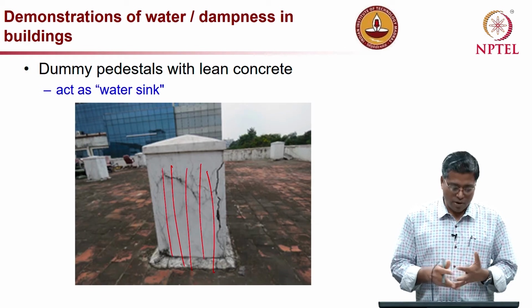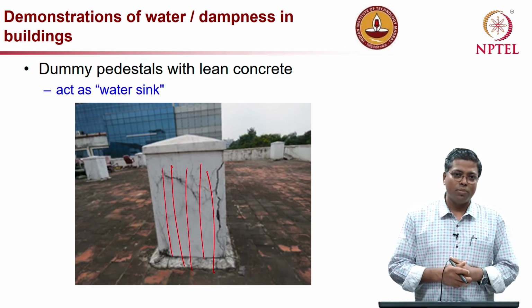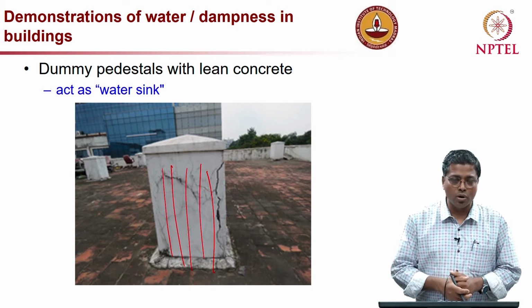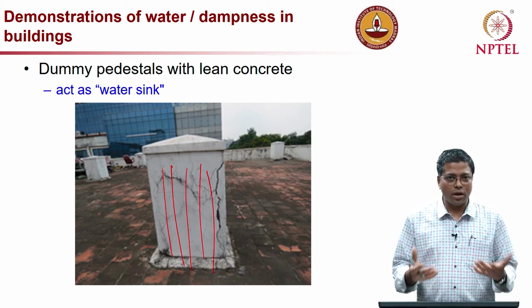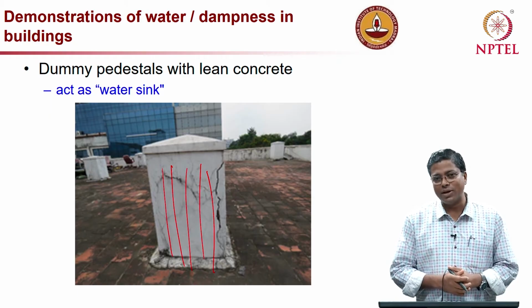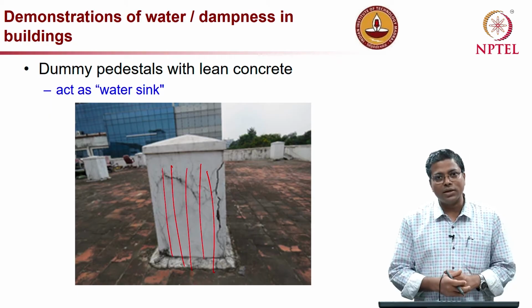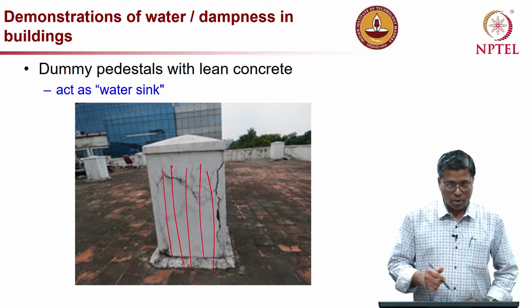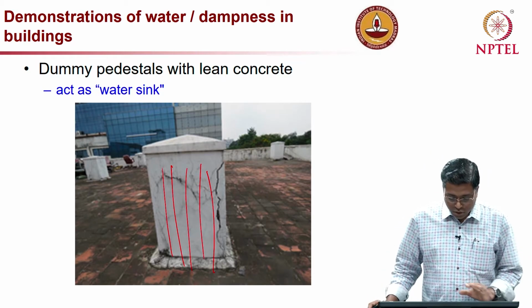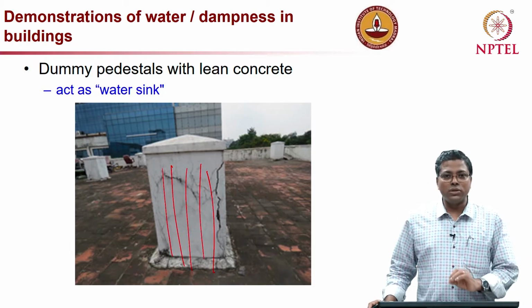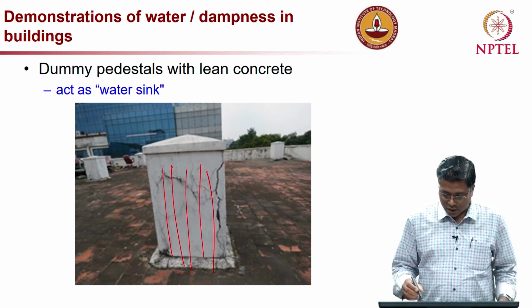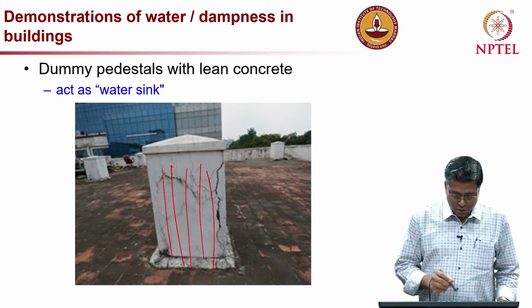And so eventually, when we really want to use these rebars as the rebars coming from the columns below, they are most often found to be heavily corroded, and we end up cutting them and then going for anchors to the columns below. So if we go for this, please go for good quality concrete, not lean concrete. That is the message which I would like to give here.